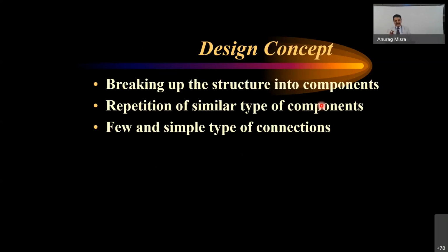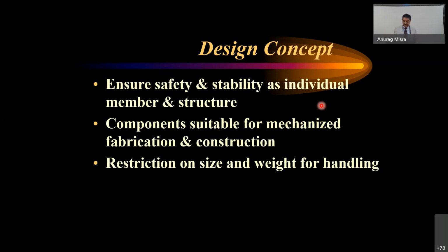So the design concept is the same as what we discussed. I'm not going to discuss right now that you have to break up into smaller pieces. You have to go for repetitive items and avoid connections, because in concrete, connections are more difficult as compared to what we were talking about there. So you have to simplify the connections. I'll give you one or two examples quickly of how we can do that.